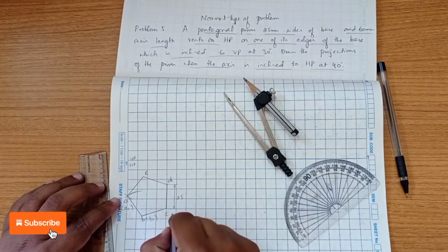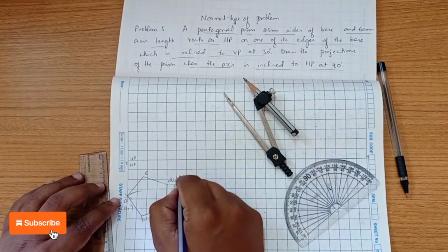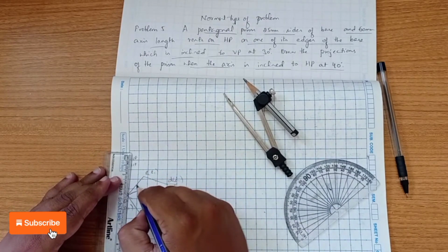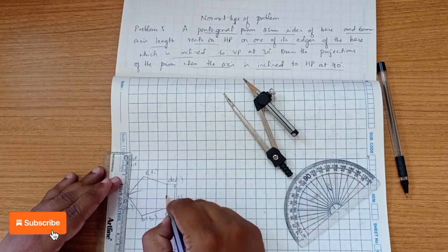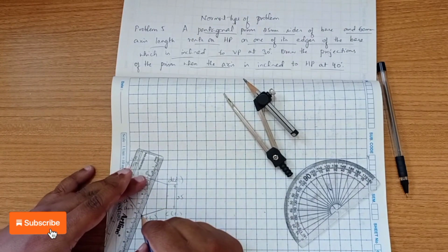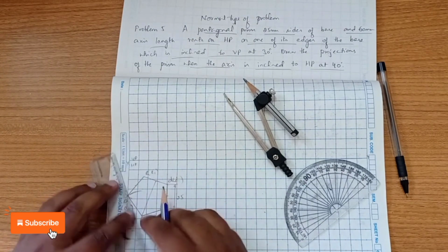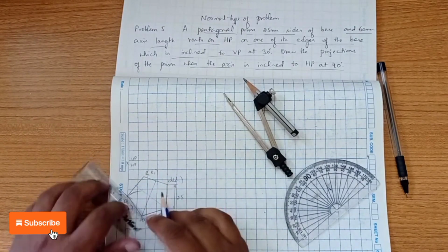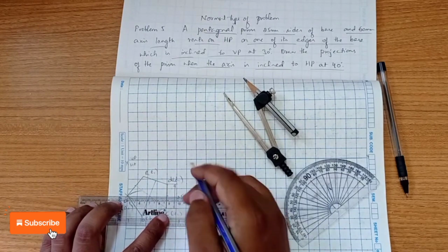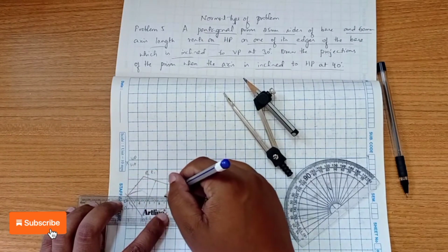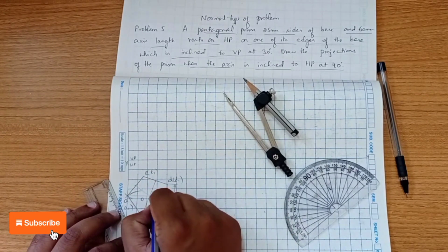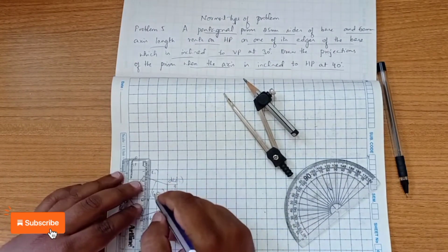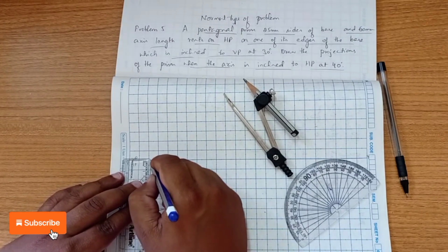All these are written in brackets because the bottom face is not visible from the top view. Now we draw perpendicular bisectors by marking the middle point of any 3 edges and drawing thin lines here. So here we are drawing thin lines to find out the center of the axis. So remember it, in a prism we are drawing thin lines. So O1. Now project it upward to complete the front view.